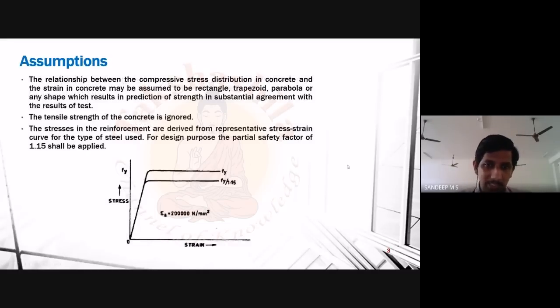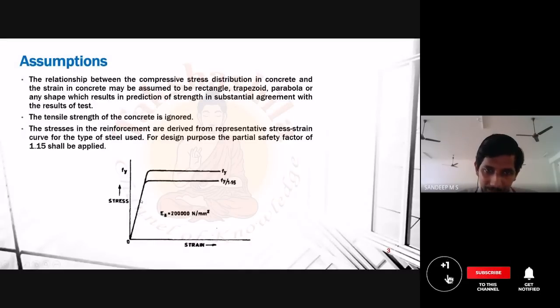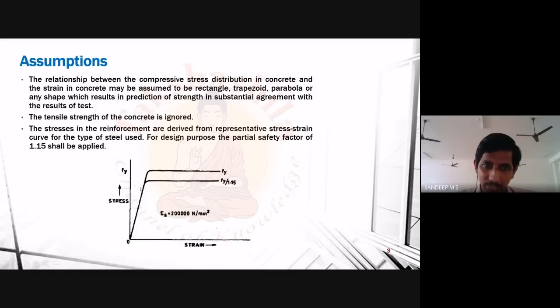So if you see the stress strain curve here, once we go on increasing the load, what will happen? If you take this point, we have zero strain here. We are further increasing the load and reaching another point. If you take the corresponding strain, we plot a line downwards, and we take the strain here. This is the strain corresponding to this load in the steel. And again, we increase the load, and we get a higher value of stress, and similarly a value for strain, and finally we will reach the yield stress of this steel, and the corresponding strain is called the yield strain.